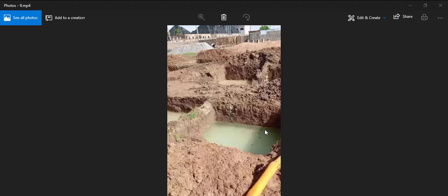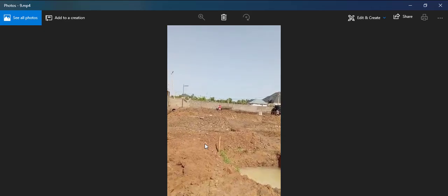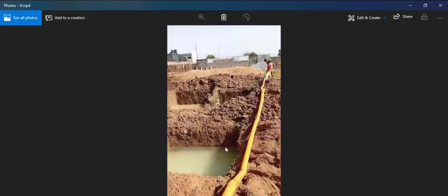So as we are pumping out the water, when it gets to almost a dry ground, because the water will be coming from the ground, you add very little water. Then as you are mixing and the water is coming out, it quickly mixes and hardens up. But if you mix with the normal water ratio, plus this water coming in, it will affect your mixture.